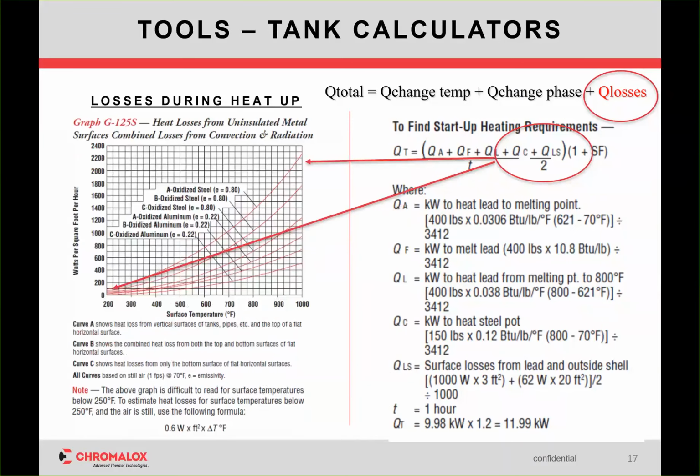And you want to maintain your losses between the two to know how much thermal input. This is there to keep you from oversizing your heater. I mean, you can size it for the worst case scenario. You absolutely can. But if it's a higher kW requirement application, you can find where you'll oversize your heater by a significant amount. And it's just important to know that calculation and that they're dividing that heat loss by 2 in a lot of these,